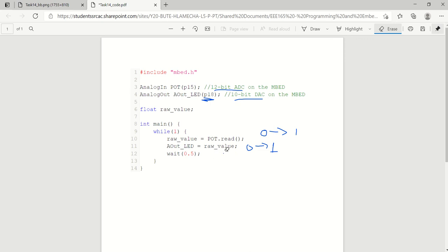So it's a bit of an introduction to analog control. We're going to do some more on it, and look at other videos which will help. But just note, at this stage, you have a couple of different analog inputs. You have only one analog output pin. Your analog input sensor is reading in a value on that pin, a value between 0 and 1 based on this conversion. A bit of maths in behind that. And then it's giving out a value onto that pin, again a percentage value based on this conversion and how much output current or voltage it's going to give. And then it loops back around.